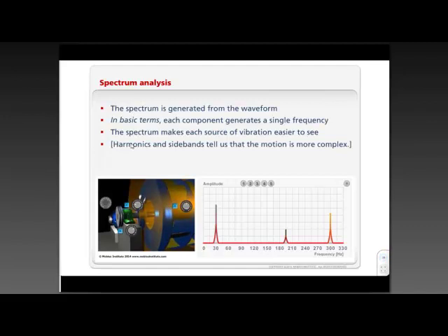If the machine, let's say, is not uniformly stiff, and or we could go into a bunch of detail, basically the sine wave is no longer nice and smooth, and we end up with something called either harmonics, which is multiple peaks, and you'll see an example of that in just a moment, or we see sidebands if the amplitude of that signal is not constant. It rises, falls, and we'll see little peaks on either side of the big peaks.